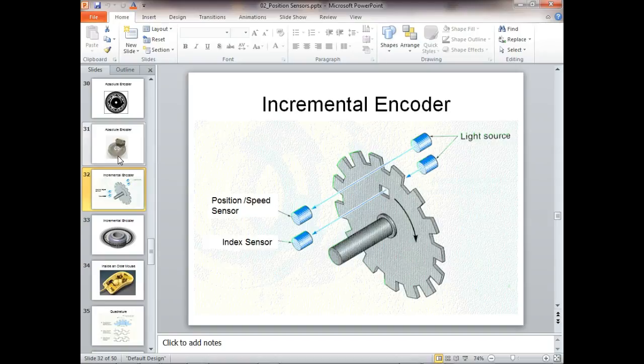So what we do is we have marks on the robot that we move it to and line up these marks, and then we redo origin. That would be called a quick origin. Or we can buy special jigs that you mount on the robot, and you touch certain spots and set what they call a factory origin.